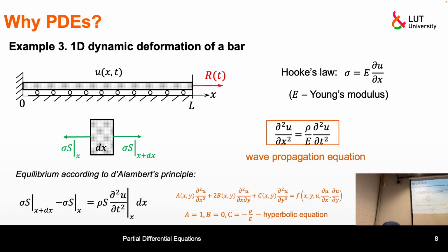And actually the cross section here, when it became thinner, then the stiffness here is already somewhat lower than it was initially. For instance, if you want to describe this type of effect, you would need quadratic terms as well. Even though it's kind of one-dimensional, if you want to account for that increase, you would be implicitly accounting for transverse displacement as well, at least implicitly. But probably better to do that implicitly if you want to consider something like that.